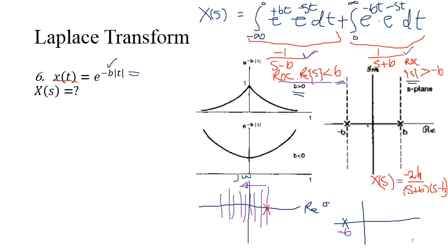If you look at the generalized expression, if s equals minus b, then minus b plus b cancels, you get 0, 0 multiplied by this results in 0, and this divided by this results in infinity. So this second expression has its ROC defined by greater than minus b, so all this region is the ROC for the second part.